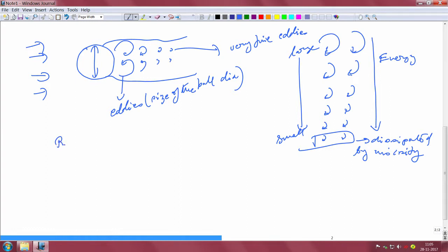So, if you have a Reynolds number for this kind of a flow, say for example, u d by nu, that is of the order of 3000, you have calculated, where u is basically the approach velocity. Usually speaking, when the Reynolds number is that high, viscosity cannot be important, because Reynolds number by definition is inertia over viscous. So, it is 3000 times higher. So, viscosity cannot be important.